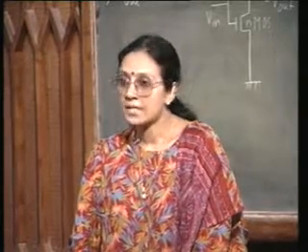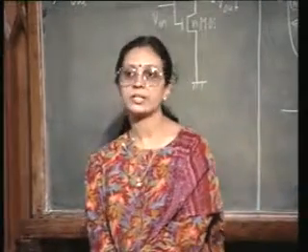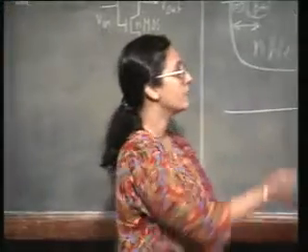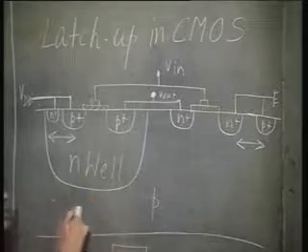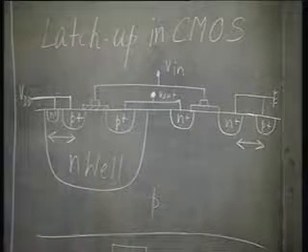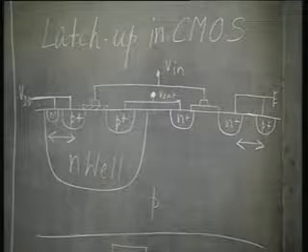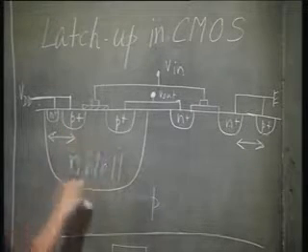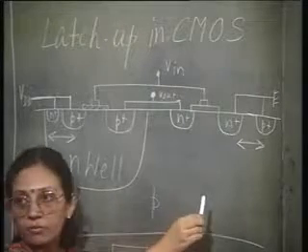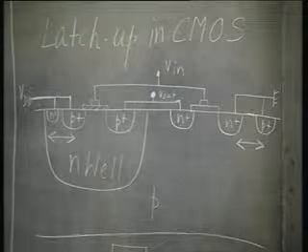And that is possible because now you have a lot of sophisticated techniques. For example, ion implantation. You can make sure that you have a very heavily doped region underneath the N-well or deep inside the p-type substrate, right. So that the current finds little resistance. When the current is flowing in this direction, it finds little resistance, but the MOSFET performance is not affected because the doping is not coming anywhere near the depletion layer.